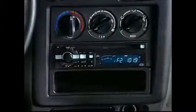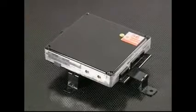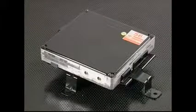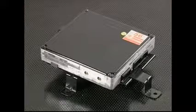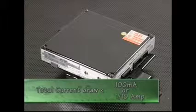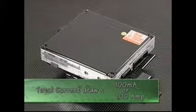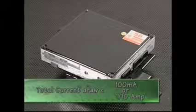There are several devices that normally use current when the ignition key is off. Most of these devices are electronic devices that use the current to retain the memory in an electronic control unit or that power vehicle security systems. On a typical vehicle, the sum total of current draw is less than 100 milliamps, or 1/10 of an amp, with many of the vehicles having a draw of less than 50 milliamps.